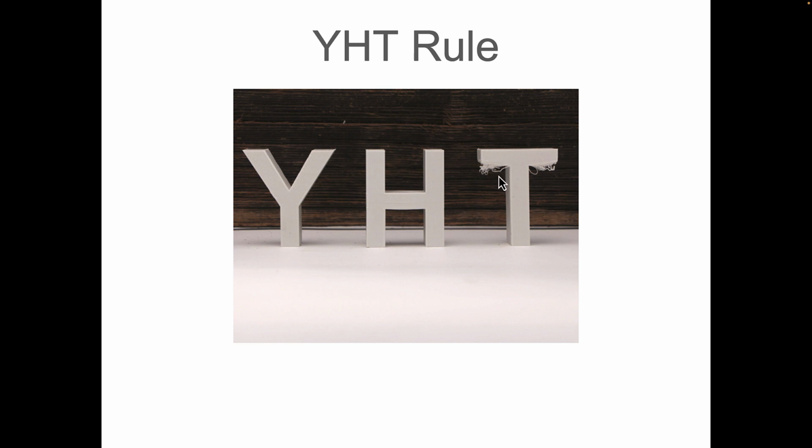Now to solve this problem, you may automatically think, well, let's just enable supports, which would work. It would create these vertical columns that would support the horizontal bar here, which you can just snap off later. However, the T is a perfect example of thinking about ways to reorient your part in order to not need supports. So you want to get into the habit of not always relying on supports.